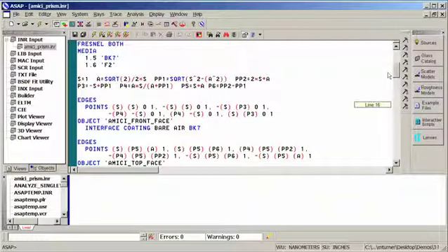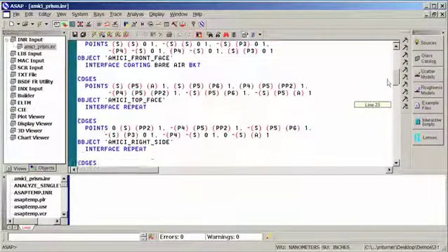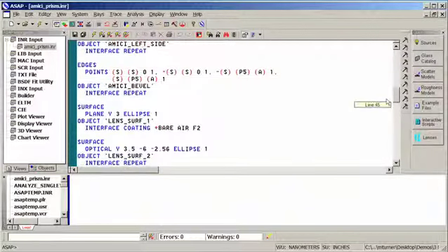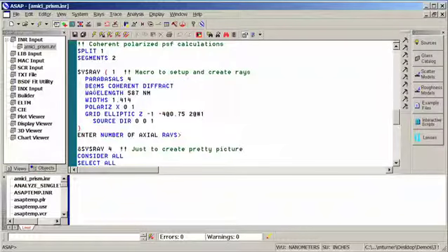We've defined the Amici prism itself with bare surfaces, so we're going to see some Fresnel effects. And to tell ASAP we're going to do coherent analysis, we simply have to add a few more commands to the ASAP script file. In this particular case, just telling ASAP to do a coherent analysis. But in this case, we're also going to define an input linear polarization.